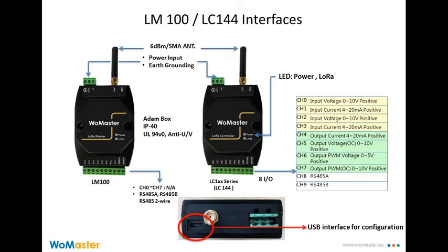In the bottom of the casing, there is the 10-pin terminal block. Each pin has its meaning as in the table. Each input, no matter the current or voltage, contains 2 channels. Output uses 1 pin only. Now, all of the open pins are reserved for the option. Last, channel 8 and channel 9 are used for the RS485 connection.